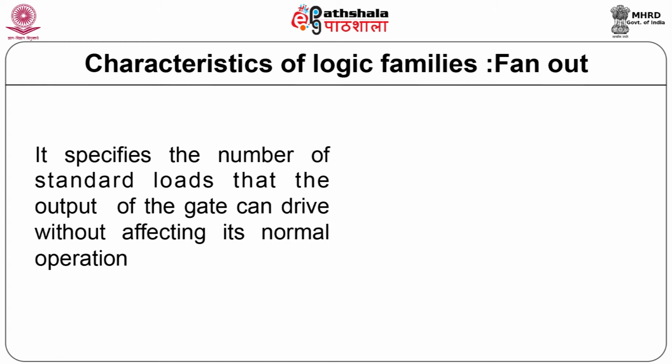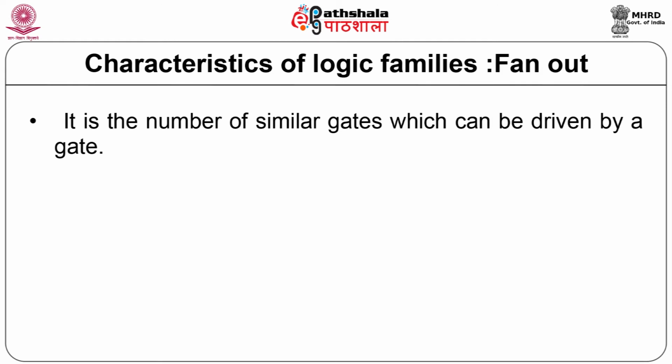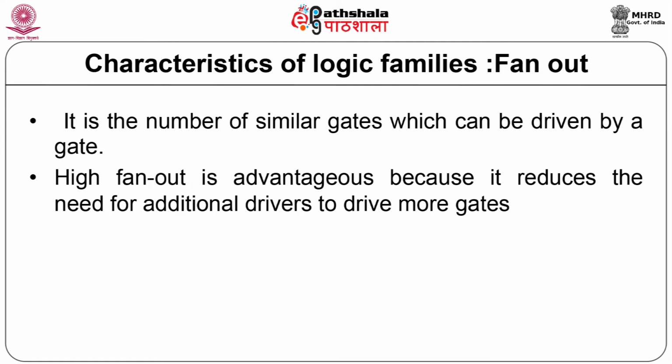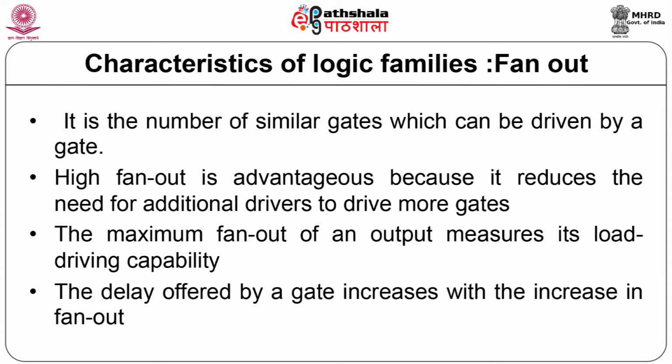The next characteristic of logic family is fan out. It specifies the number of standard gates or loads that the output of the gate can drive without affecting its normal operation. It is the number of similar gates which can be driven by a gate. High fan out is advantageous because it reduces the need for additional drivers to drive more gates. The maximum fan out of an output measures its load driving capability. The delay offered by a gate increases with the increase in fan out.